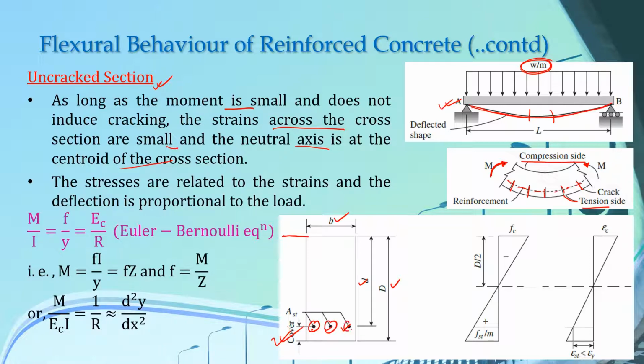If these are our reinforcement, let us say I have enlarged them, then draw a line through the middle of these bars, the distance from the topmost compression fiber to this middle line is known as the effective depth, or small d. And the distance between the centroid of this bar to the extreme tension fiber, we call cover.